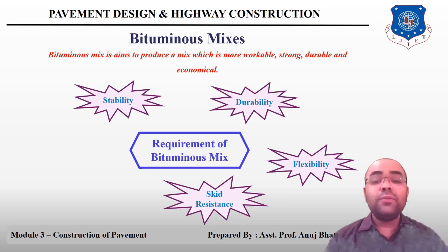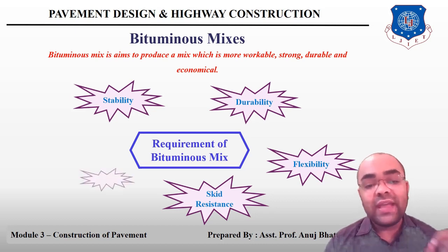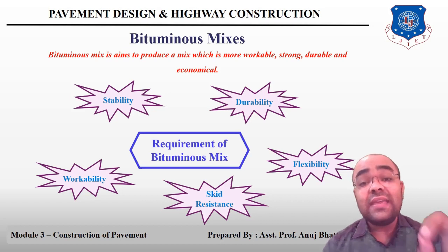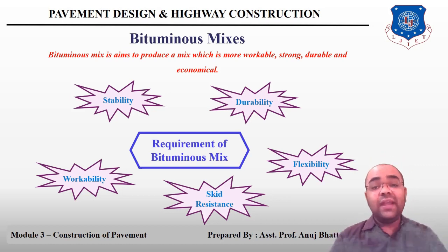The next bituminous mix requirement is workability. Workability is the ease with which the mix can be laid and compacted, and formed to the required condition and shape.